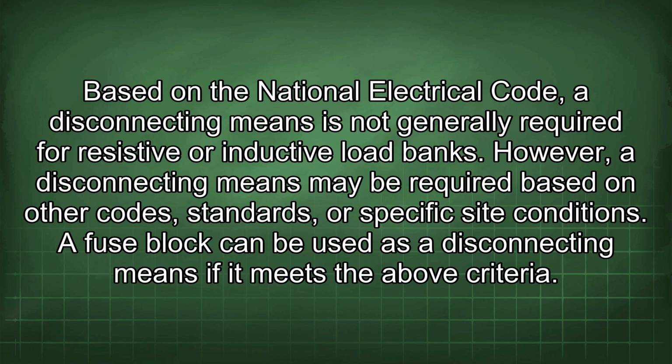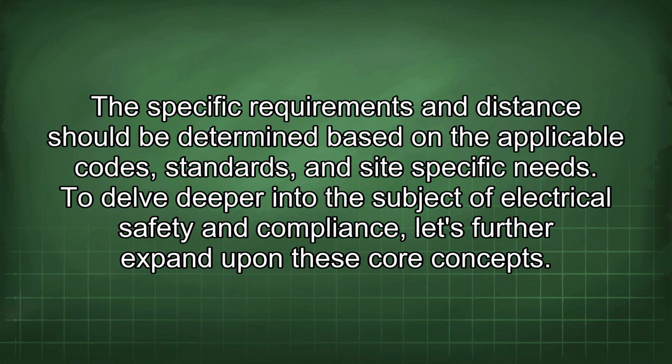Based on the National Electrical Code, a disconnecting means is not generally required for resistive or inductive load banks. However, a disconnecting means may be required based on other codes, standards, or specific site conditions. A fuse block can be used as a disconnecting means if it meets the above criteria. The specific requirements and distance should be determined based on the applicable codes, standards, and site-specific needs.